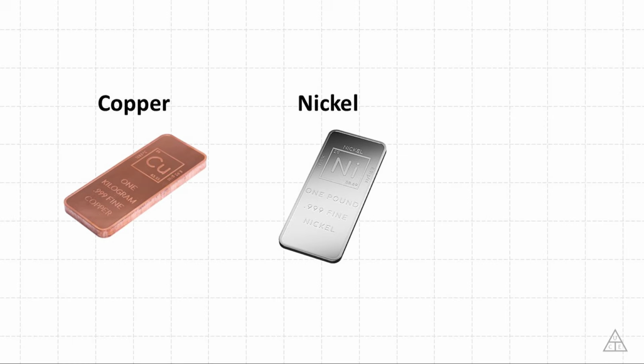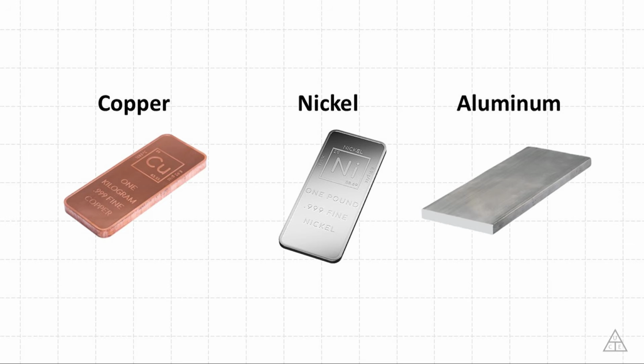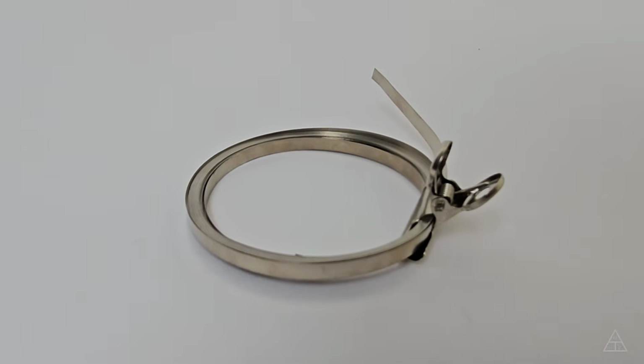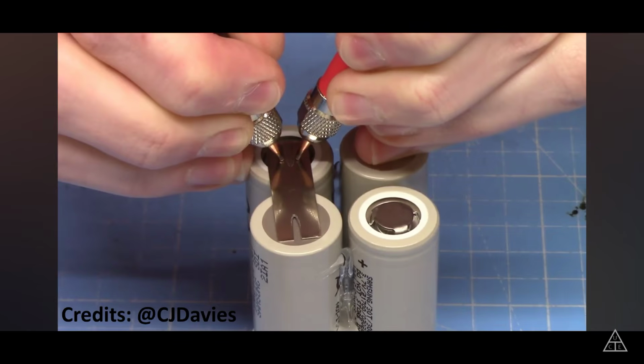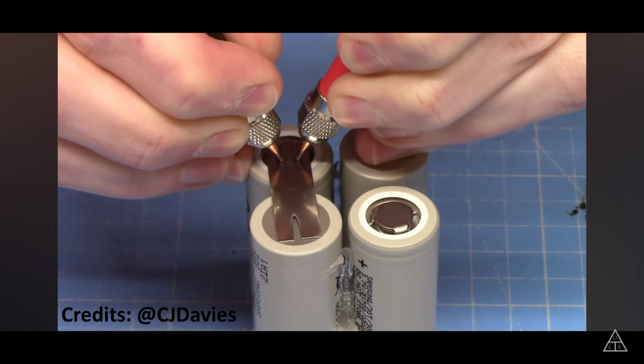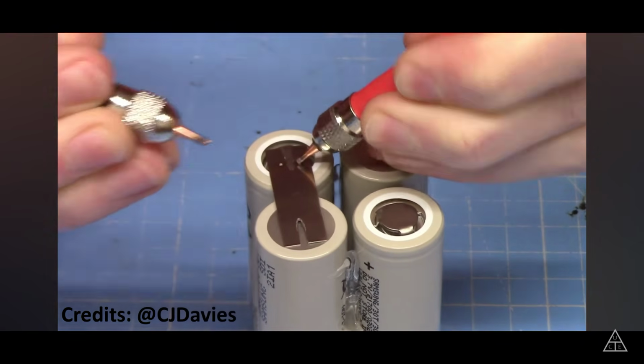Well, now that we decided the chemistry of the battery cells that we are going to use, we can move forward to deciding what will be connecting them together, or the busbars. They are usually made out of copper, nickel, or aluminum, and can come in two different formats that are metal strips or usually thicker screwed-in-place busbars. The strips usually are welded in place using a technique called spot welding. Spot welding machines usually are quite expensive, and in my case I try to avoid using them. That's why the battery cells that I chose have a place to screw a busbar in place.